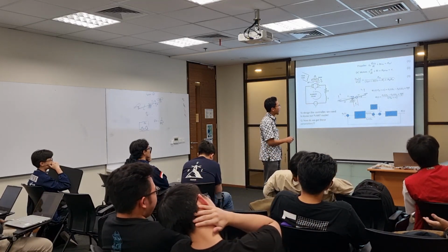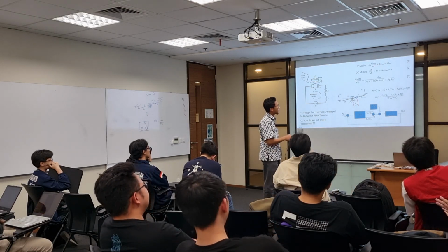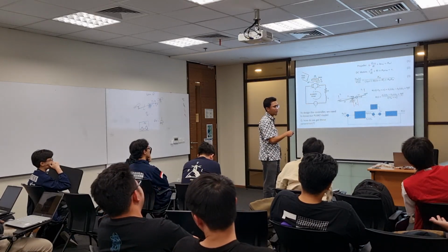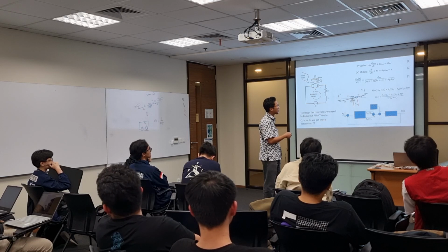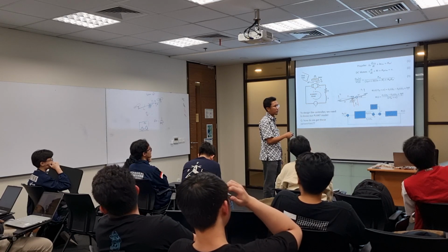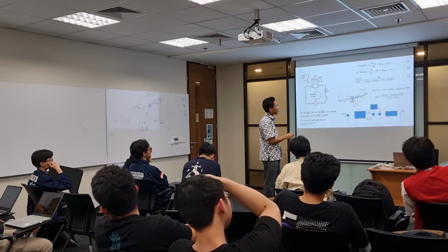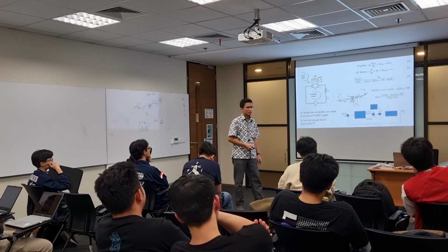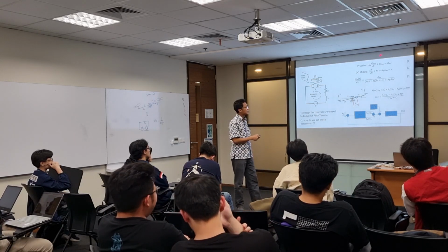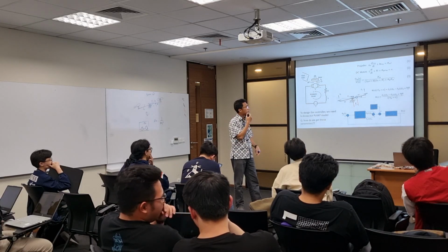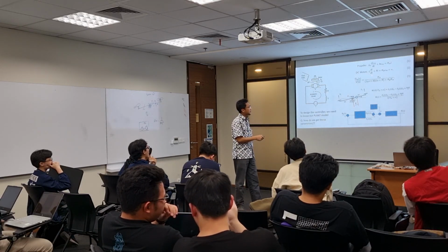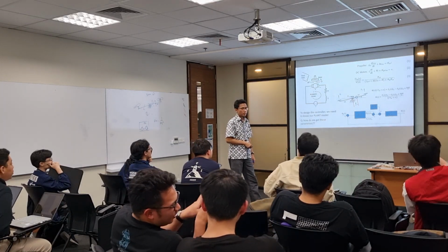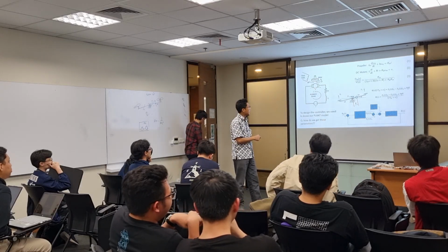Number 1 and 2. Okay, number 1 is simply mass times acceleration. Okay, this is mass, angular. And then this is the torque. The omega is speed, right? So you take the derivative of the speed, you get acceleration. Mass times acceleration is equal to the torque applied. And then this one is just coming from Kirchhoff's law, at the current.